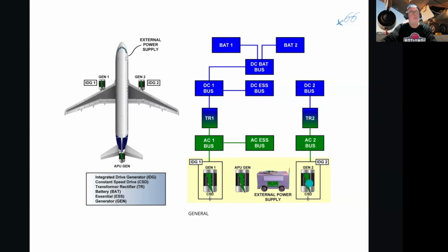These are the normal flows, and we have electrical power separation, obviously, because we want to keep the loads in an adequate arrangement, and we are also duplicating things. Invariably, everything on the left-hand side gets supplied by AC bus 1, and everything for the right-hand side, the number 2 systems, gets supplied by AC bus 2.